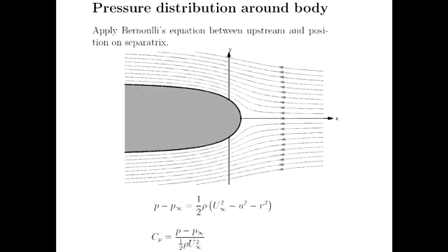So it's defined as p minus p infinity, which is really the pressure force that's going to be acting, there are some area terms that have cancelled out here, divided by a half rho u infinity squared, which is the inertial term or the inertial force. If you haven't come across it, it should at least look somewhat familiar from seeing lift or drag coefficients in other courses.